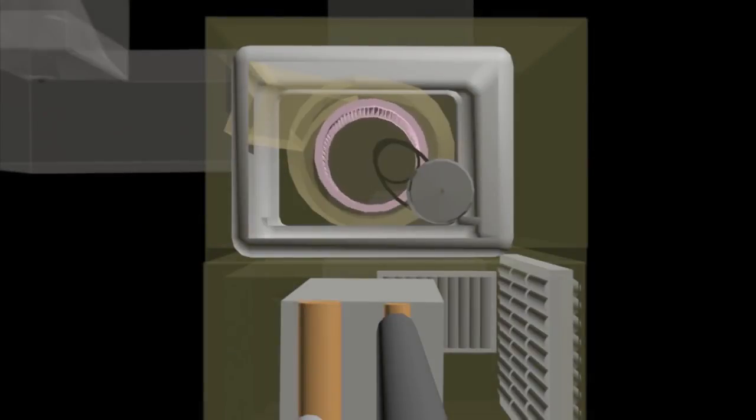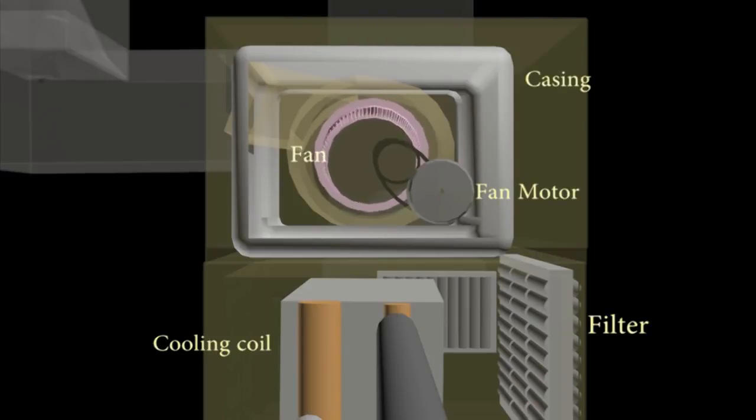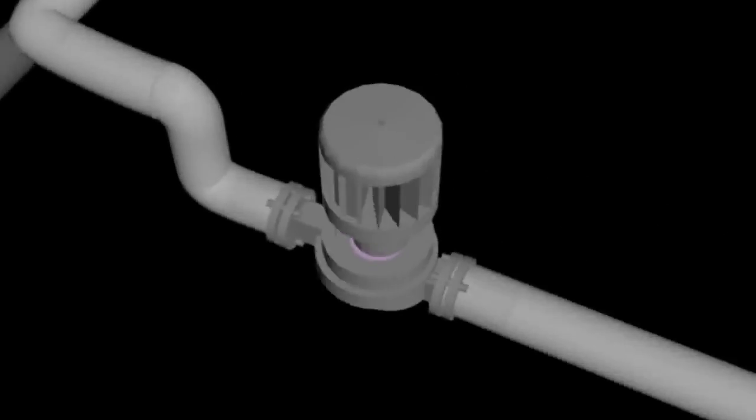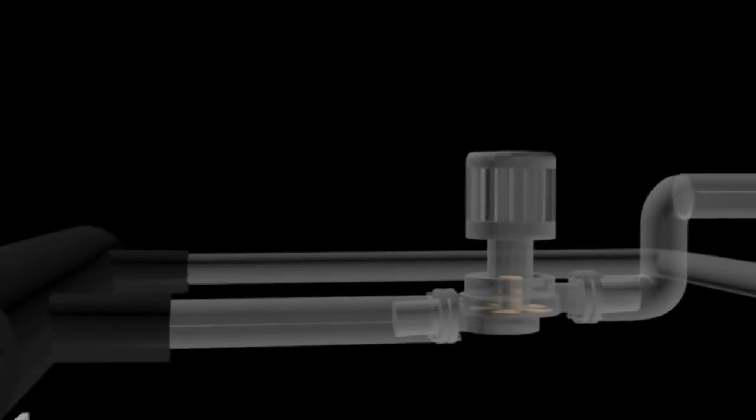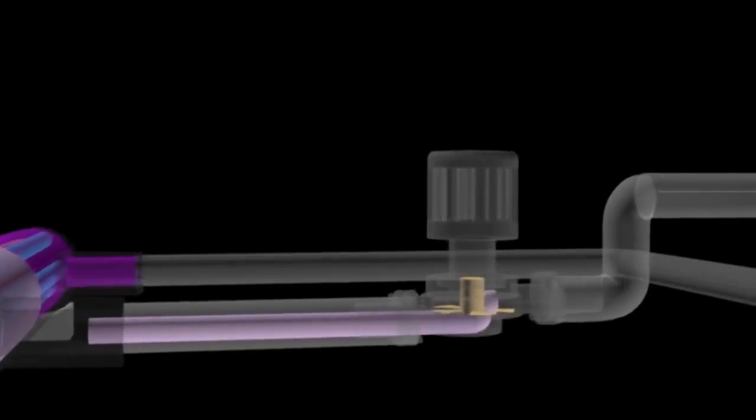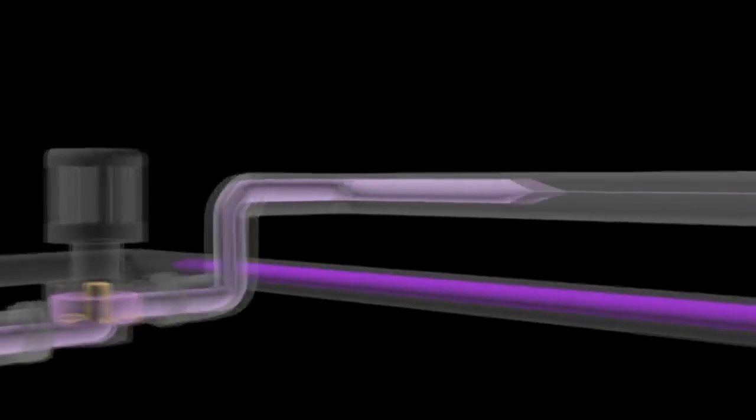The air handling unit is a place where cold air is produced before it is distributed. It consists of several key components such as the cooling coil, fan motor, belting, filters and the casing. Chilled water produced in the evaporator will flow into the air handling unit through a pipeline which is marked with dark blue color. This chilled water is known as chilled water supply.